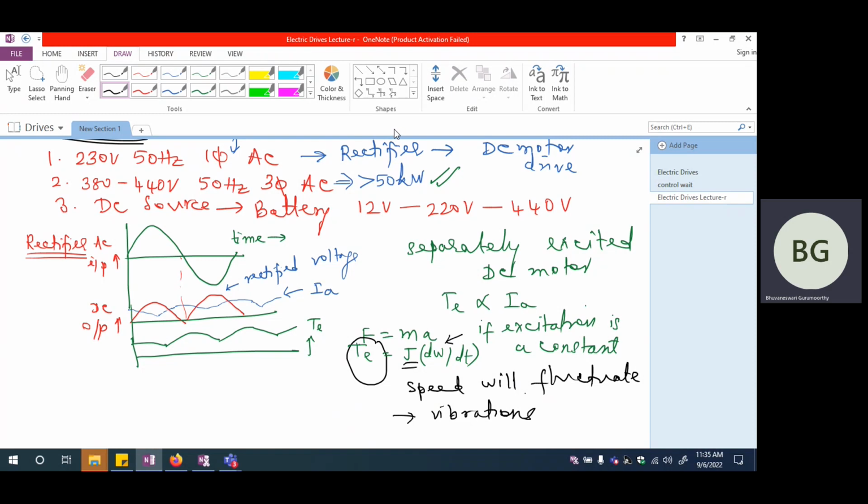One line can be printed on the top of another line. So you may not be able to read the book at all if you are having vibrations in the motor shaft, which is running the printing press. So in general, in the single phase case, because you are going to have oscillations in the torque and oscillations in the speed, vibrations will be there in the shaft, the product quality will not be good, especially at larger ratings. Even smaller vibrations can cause cracks in the shaft.